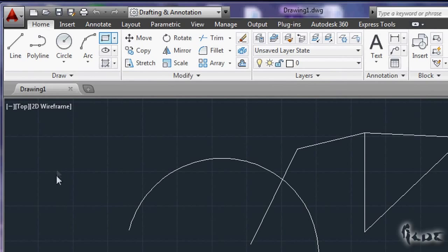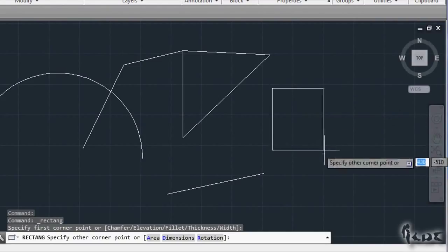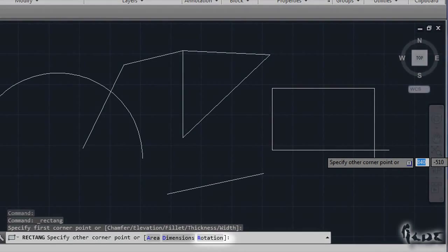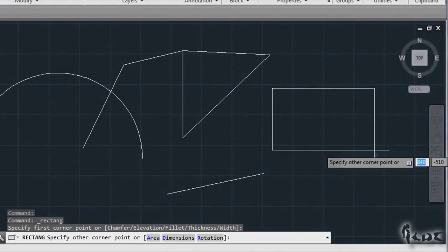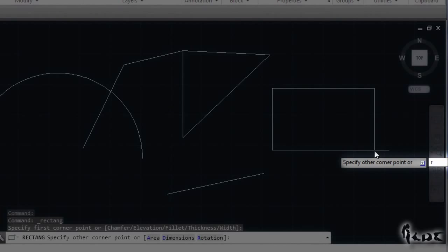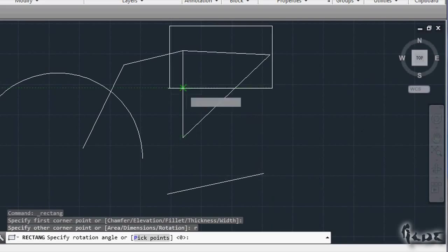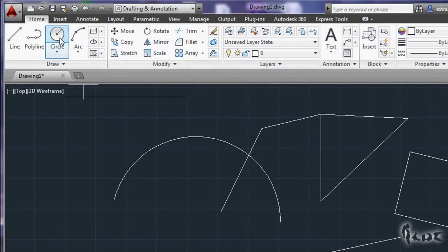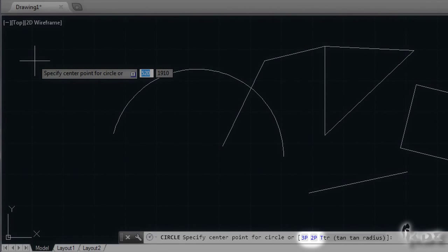After you set the first point, you can put a precise area or rotation. If you want to rotate your shape, just type R in the white slot next to your pointer. This is used to type a command. If the command rotation has the blue letter R below, it means that you need to type R in such white slot to run it. Then press the Enter key to enter the command. Make sure to pay attention to this, because for some commands you need to type more than one letter.